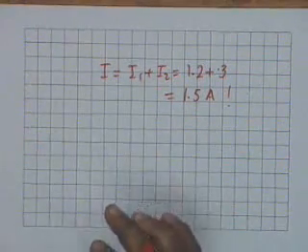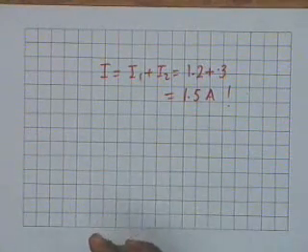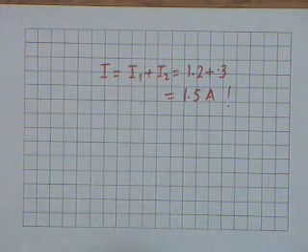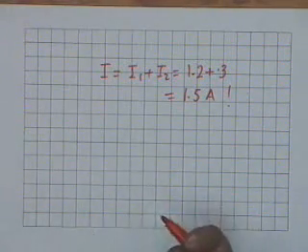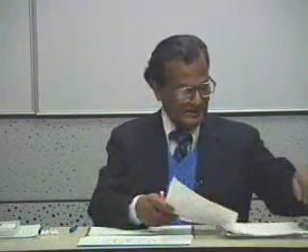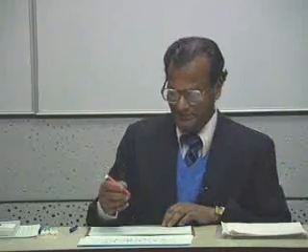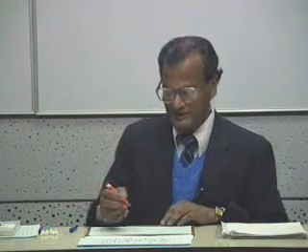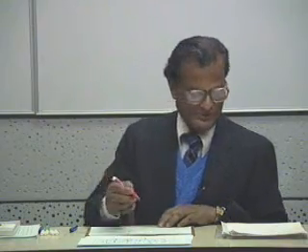Here also you see we didn't have to write any loop equation, node equation, branch formulation or anything. We didn't even make any source transformation. We simply applied superposition. All right. So superposition does help you to solve problems. There are some other examples in the tutorial sheet, number 2, particularly on the back, and I urge you to try solving some of them by superposition.